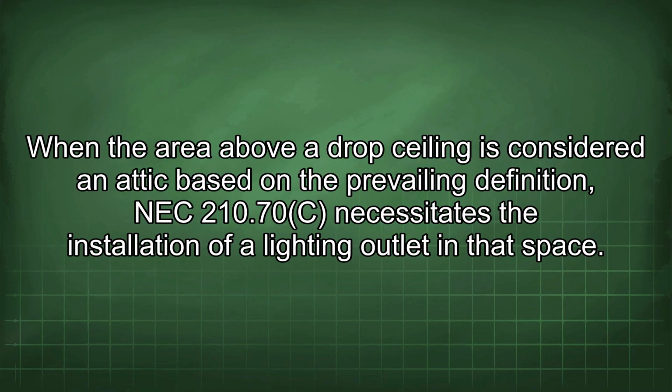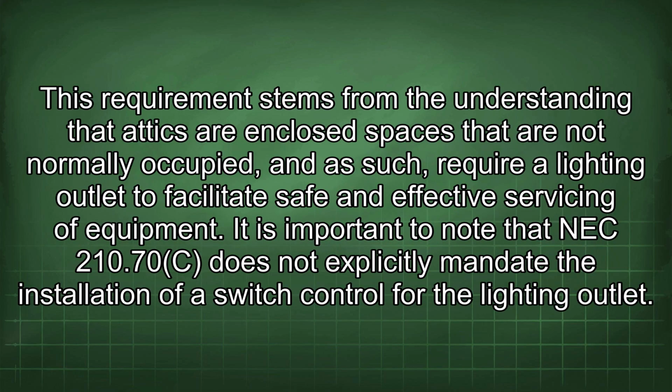When the area above a drop ceiling is considered an attic based on the prevailing definition, NEC 210.70 necessitates the installation of a lighting outlet in that space. This requirement stems from the understanding that attics are enclosed spaces that are not normally occupied and as such require a lighting outlet to facilitate safe and effective servicing of equipment.